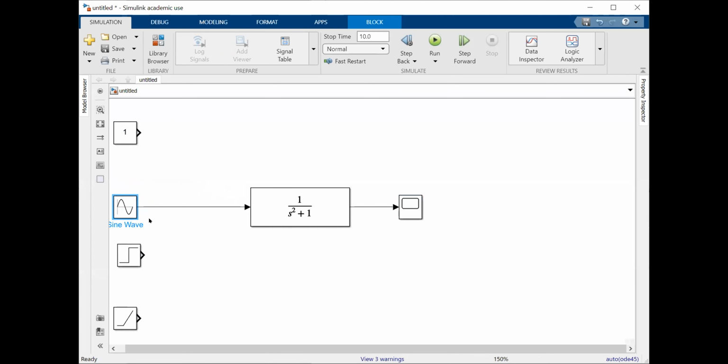I don't see it here very quickly, but if you go to simulation time step and change the time step, you'll be able to get some refined results from your simulation. So this needs a change in the time step, but you will be able to get a very clean signal, or you will be able to see a very clean sinusoid.